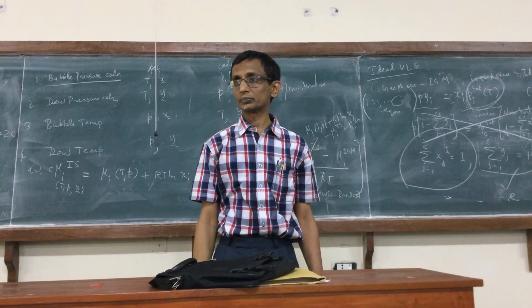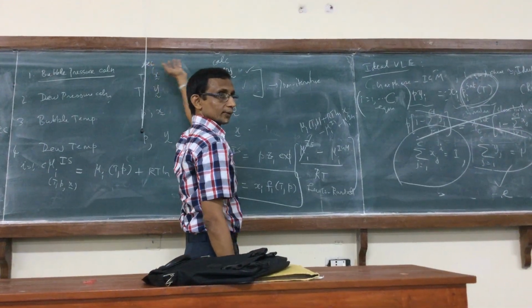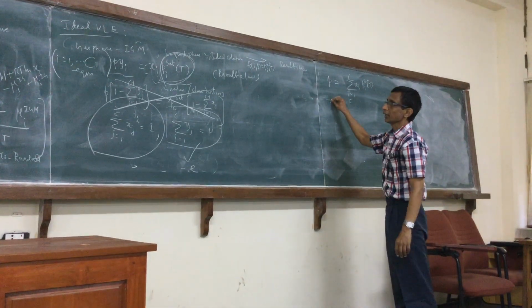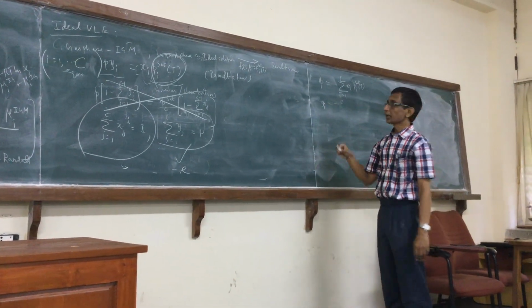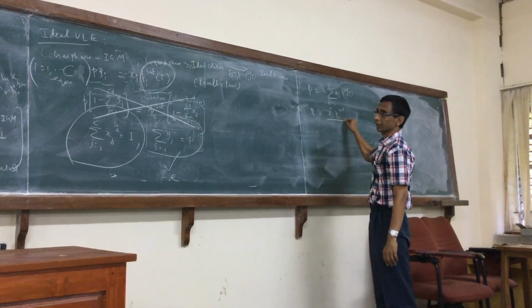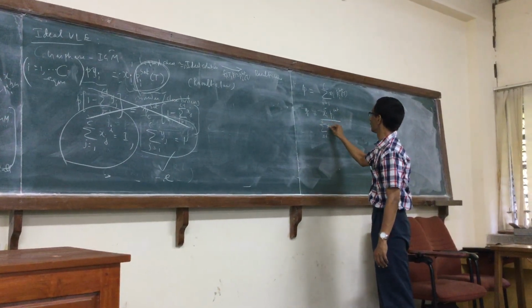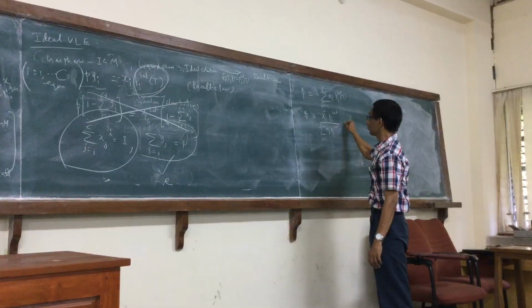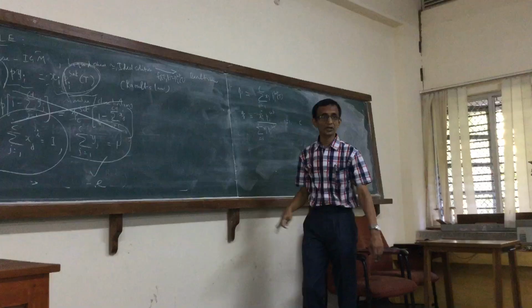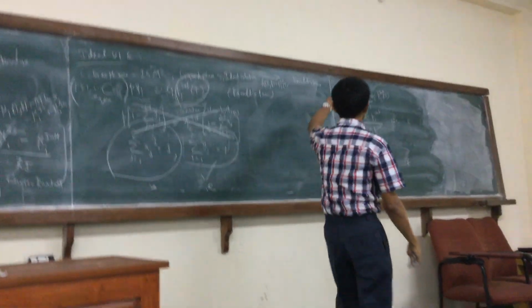That is the bubble pressure. The xi is known and specified. X, T is also specified, so obviously it gives an explicit expression for the bubble pressure. And of course, yi, which I don't know initially, can simply be easily calculated by xi pi sat by P. Of course, I can write the P is this, so here I write sum over j equal to 1 to C, xj Pj sat, for i equal to 1 to C. Clearly, the mole fraction constraint will be satisfied because those equations have been obtained by satisfying the mole fraction constraint.